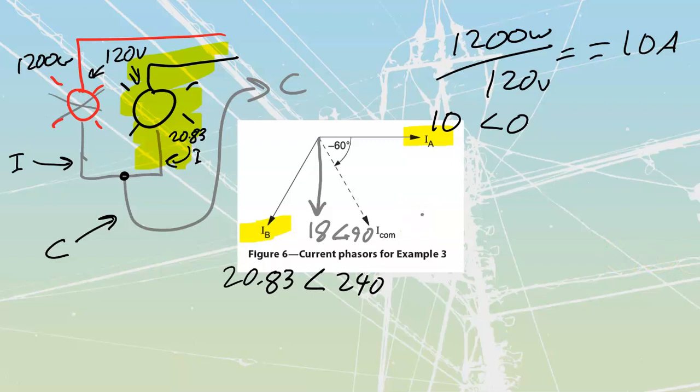It's always going to end up between, so if we've got unbalanced currents and we have got a common conductor, we are still going to end up somewhere in between those two values that's going to be carried back along there. Ultimately, whatever is delivered out to a load has to come back in, and we're proving that. This is just Kirchhoff's law of current. Whatever current enters a node has to return as well.